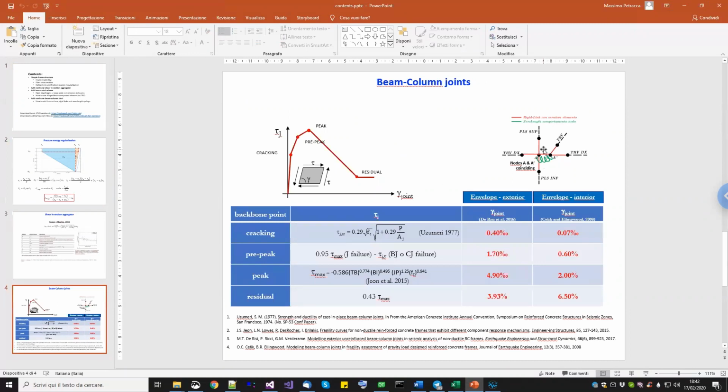So basically, if we have two beams and two columns here that join, we're going to duplicate the node of the vertex. Between these two duplicated nodes, which are actually coinciding, we will create a zero-length element with a spring in each of the directions of the coinciding beams.